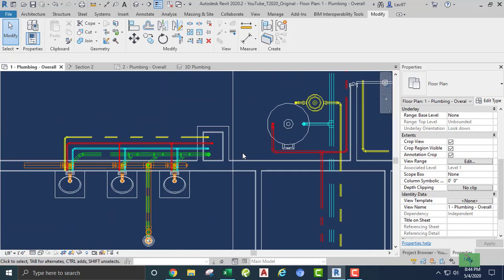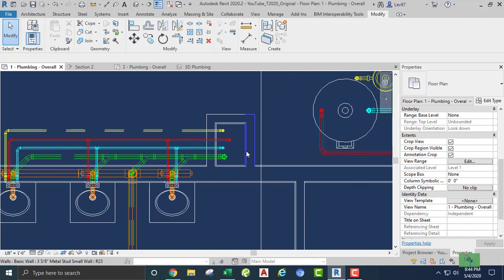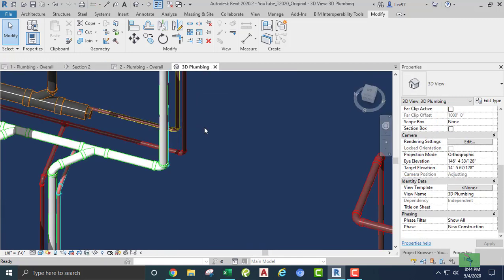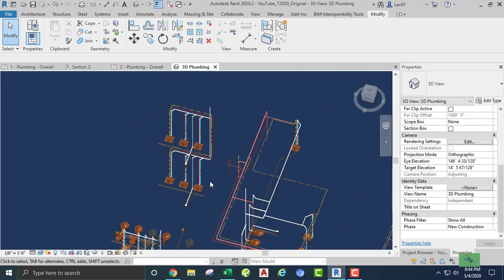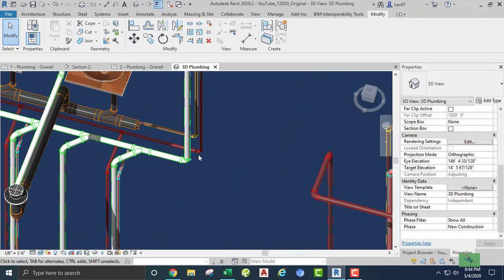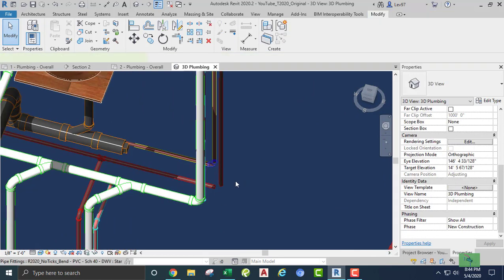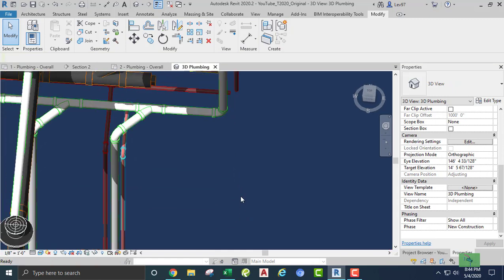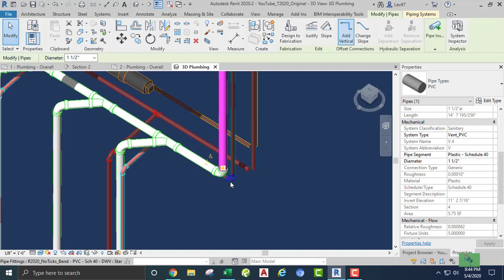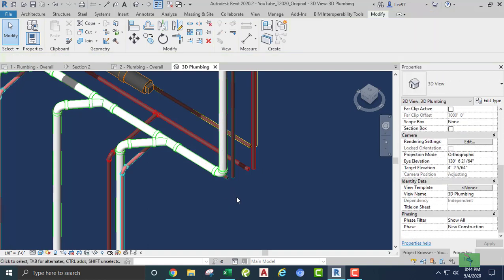Okay, from, where are we, first floor, hot water. Okay, so what we do, go to 3D level, right? Go to the first floor, take off here, and hot water return here. And what we can do, we can look at just a bit so we can take that off.